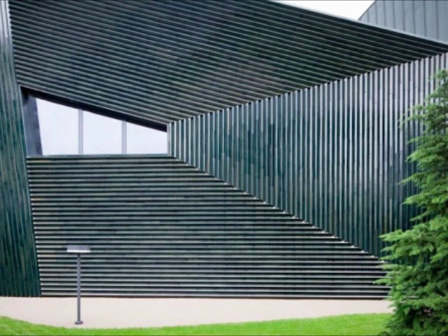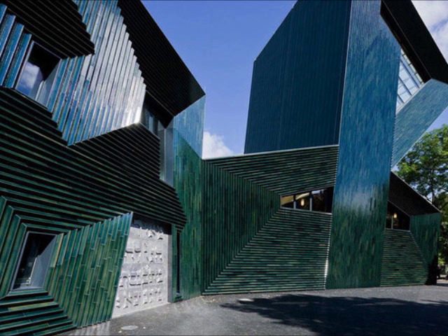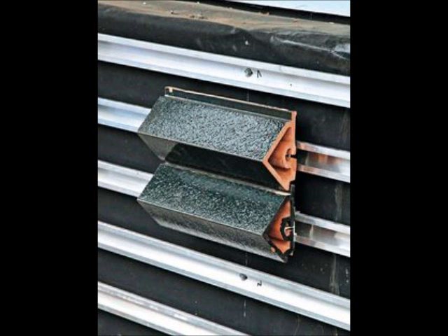Iridescent dark green ceramic elements arranged in concentric patterns around window openings give the exterior wall surfaces a 3D effect. The extruded sections were then produced in varying lengths and beveling angles to achieve the design's zigzags. The elements are fastened to the supporting structure via aluminum rails that are glued to their backsides.